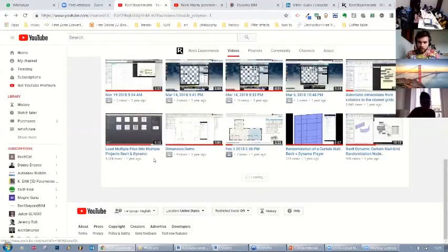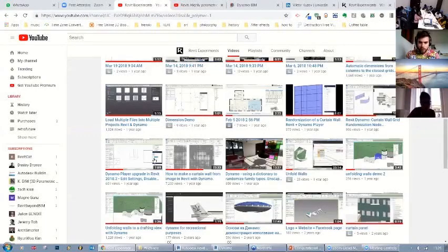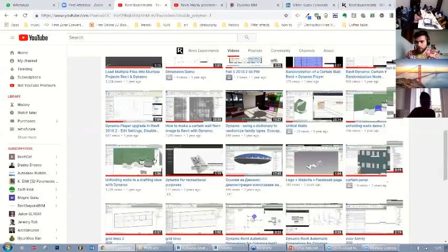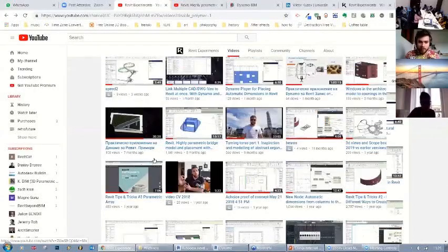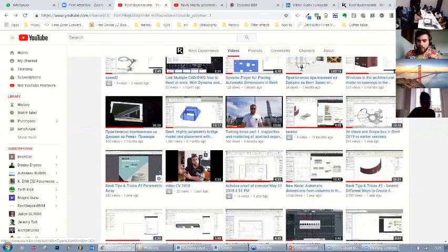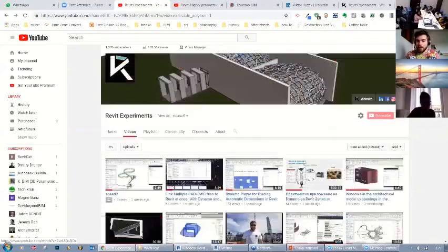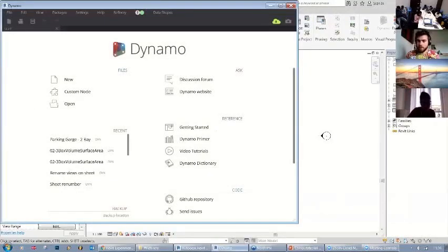Yeah, I've done a lot of scripts for dimensioning that are made in Python because it was actually better. For example, right now, the dimensioning tools in Dynamo lack some functionality, so you have to use Python to make something more complex.